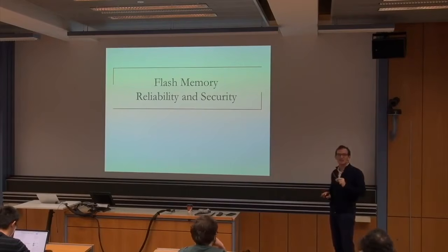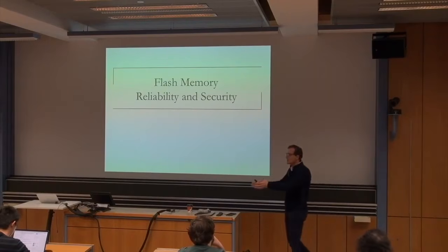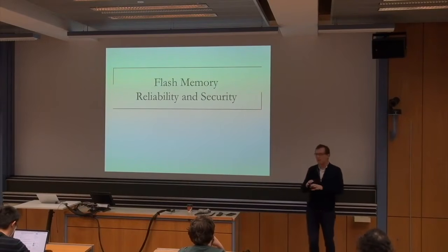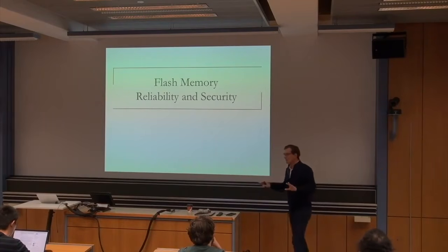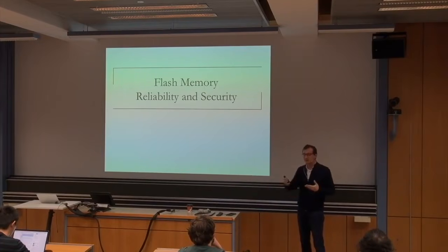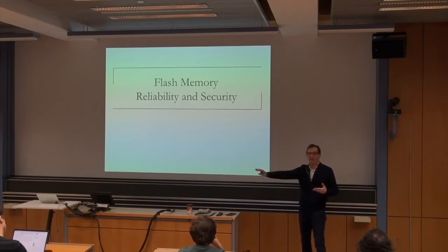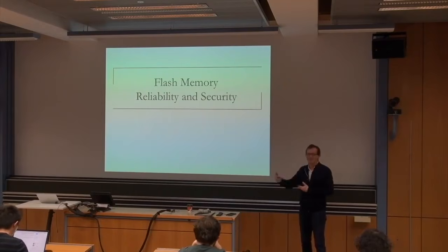You read the page. What do you do? Well, what you do is actually have blocks that are writable at that moment. So you have a set of blocks. Some of them are erased. Some of them are currently being written. And some of them are valid, meaning you already have valid data inside them. And the flash translation layer needs to keep track of them. If you want to read a page and write to it, what you do is you read the page, modify the value, and write it to some other block that you're currently writing to. Which means that you actually remap the page, right? You remap the page from this location to this location.